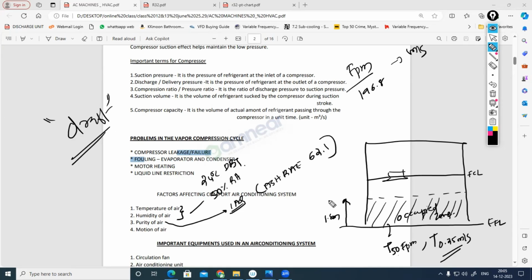That's why when we are designing the air terminal systems, we have to make sure that within the occupied zone, the air velocity is within 0.25 meter per second. That's why the motion of air is also important. Not only that, sound is also important. Each and every space we design, we have to maintain an NC value, noise criteria value, with certain decibels. As a thumb rule, most spaces will be considered at 30 decibels.